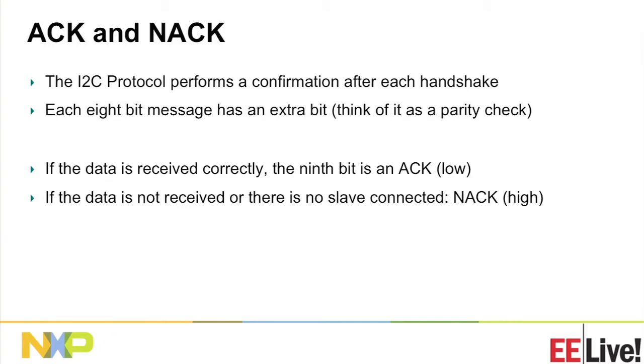So for the observant person, if you take a device off of the bus because the bus is physically removed, say your device has modules and you take a module out, the processor that's talking to that device will get a NAK each time it tries to talk to it because the device is physically not there and the bus is pulled high by the resistors, so you will get a 1 signal back at the 9th clock period.